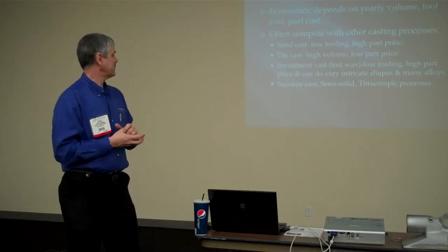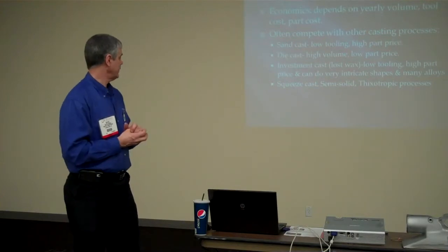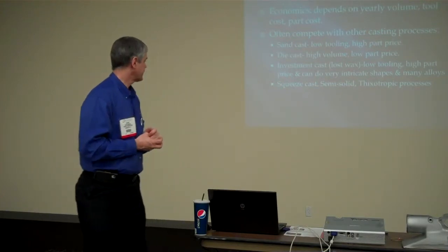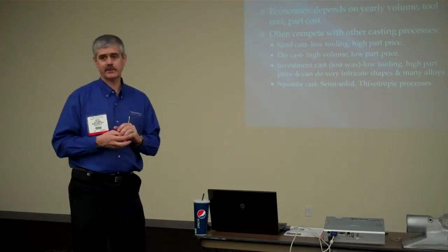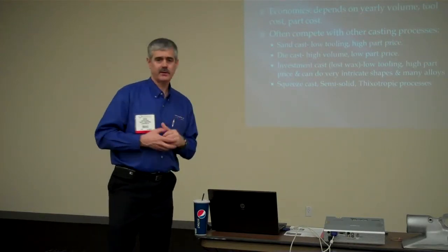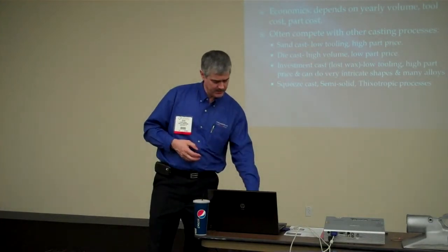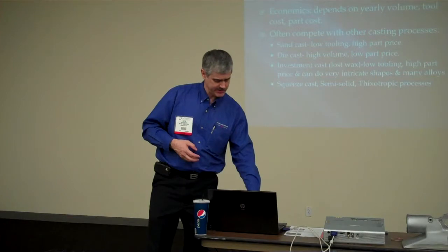Investment cast is another option, the lost wax process. Low tooling, high part price, can do a lot of different alloys and very intricate shapes. And then there's a few specialty processes. You don't see a lot of those out there on the floor. Semi-solid, thixo, and squeeze cast. Those are for very unique applications, I would say.